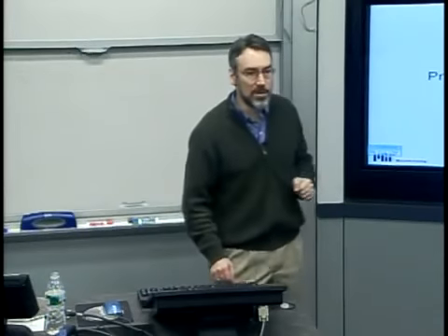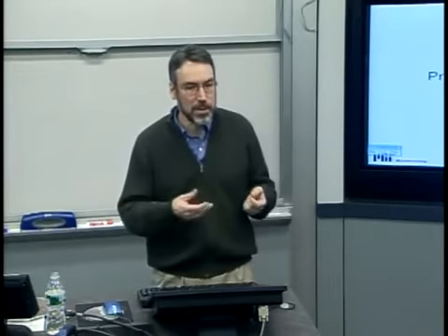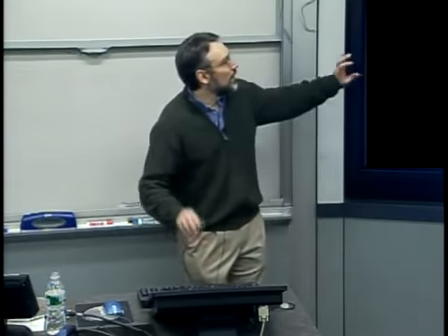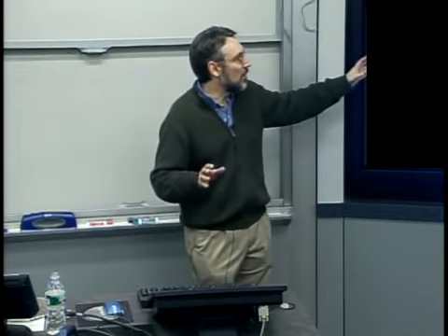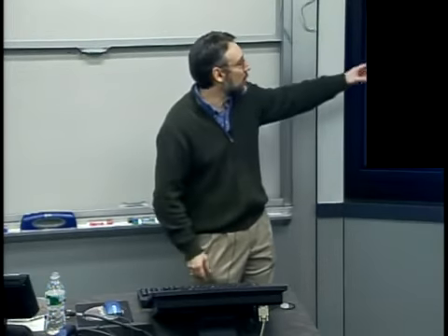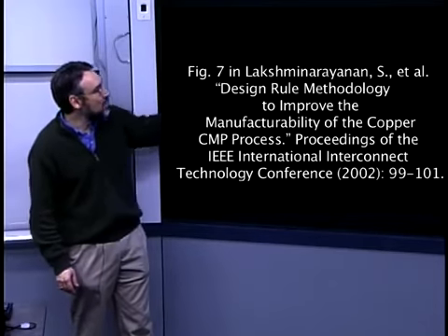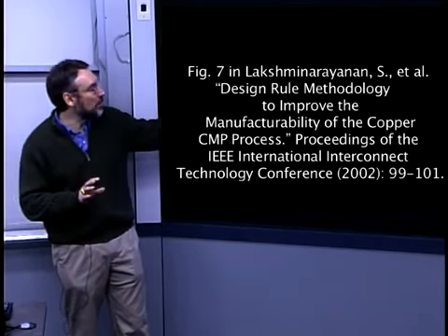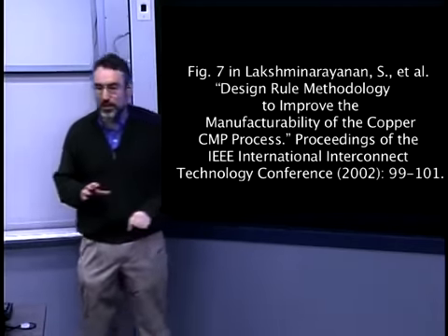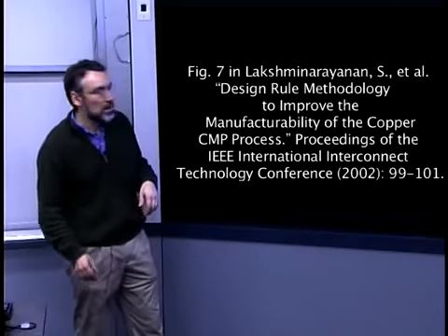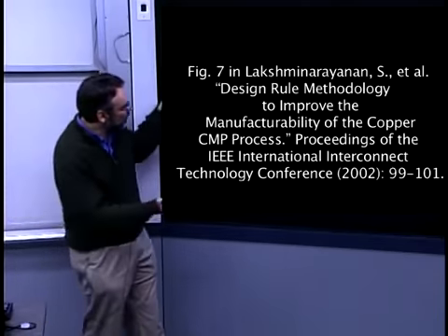One can also use those kinds of models to play with process parameters and empirically, as a function of the process conditions, minimize these systematic sources of variation. And one approach that is dominant in a number of industries is a capturing of these dependencies on design features like line width or line space and what is a good region to be operating in, these ideas of design rules. And so, in fact, this is some work from LSI Logic looking at the copper interconnect space and saying,